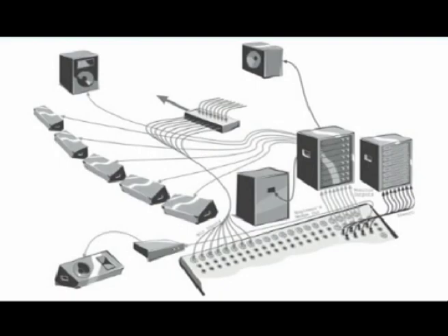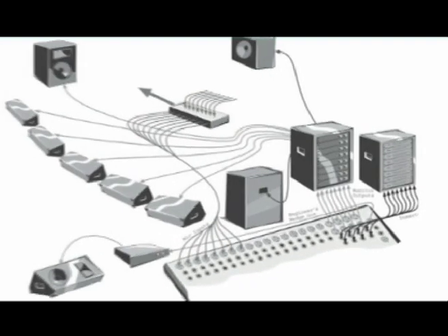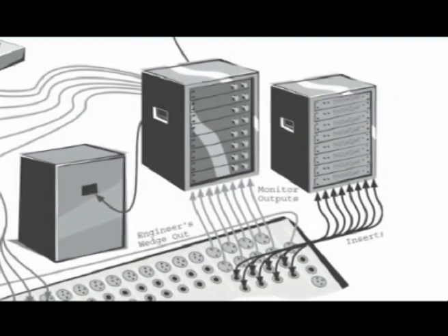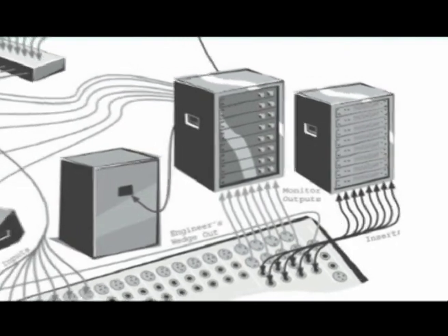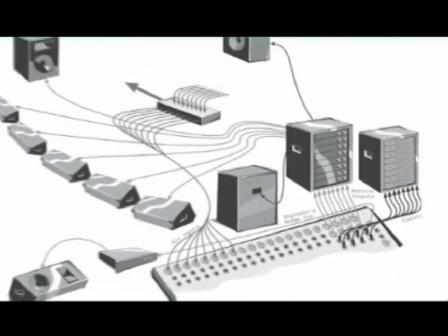It's a good idea to put a graphic equalizer on each monitor output. Then you can ring out the system in the same way you did for the main PA. Just remember that you need to do your final ringing out with both the monitor and main PA set to their normal operating levels.